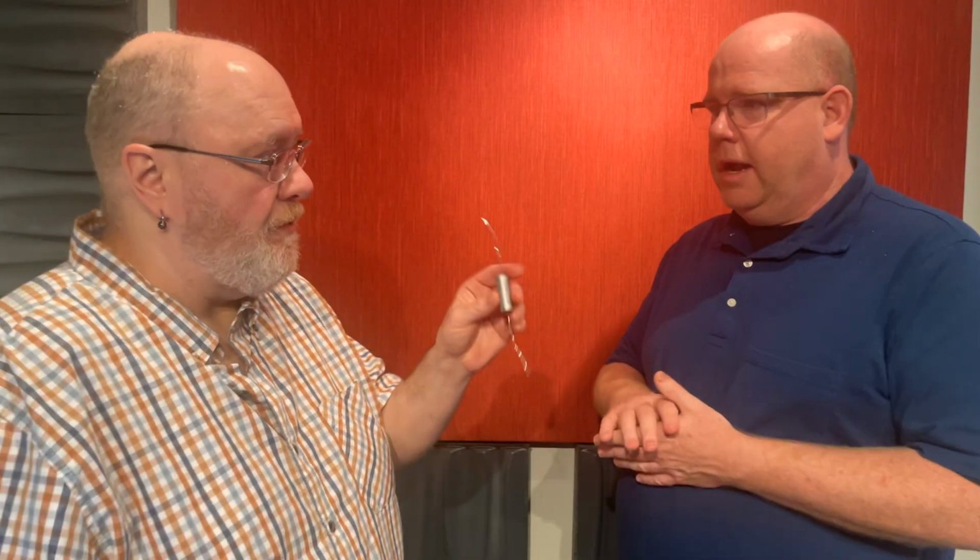And I tell people if you're looking at a speaker brand to buy, try to see if you can find a picture of the internal crossover. And it will tell you a lot. The better you can learn how good parts matter, the better purchasing decision you can make. The biggest thing I say to people, make sure it's at least got polycaps and not electrolytic capacitors. I love it when speaker designers have on their website a photo of the crossover. Tells you a lot. Well, they're not afraid to show you. That's the biggest one.